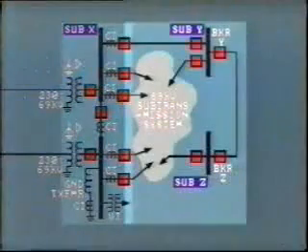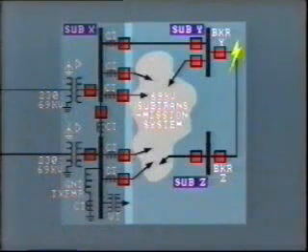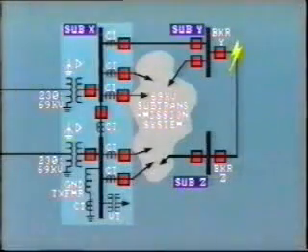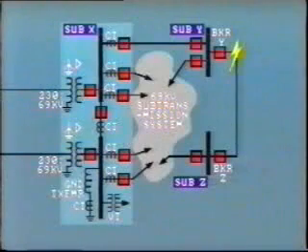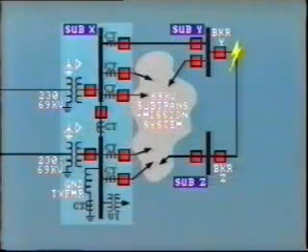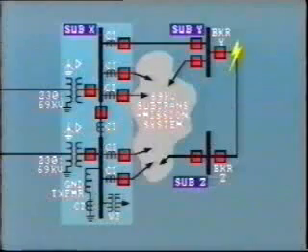Here we have a fairly extensive 69 kV subtransmission system that experiences a fault on the tie line between substations Y and Z. The 69 kV system is delta connected, but effectively grounded through zigzag grounding transformers located at substation X. Notice that all the oscillograph equipment is installed in substation X, remote from the fault location. In spite of this distance, we can still obtain a great deal of information from the recordings.